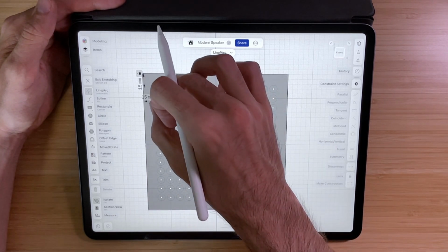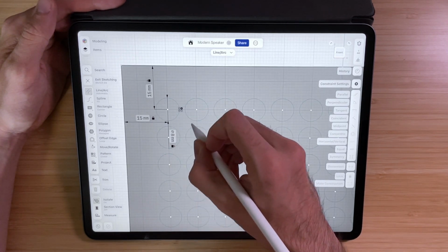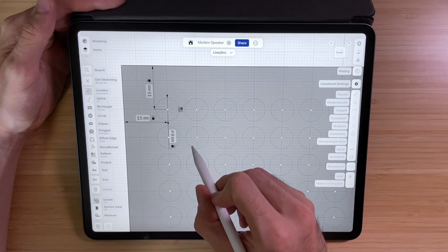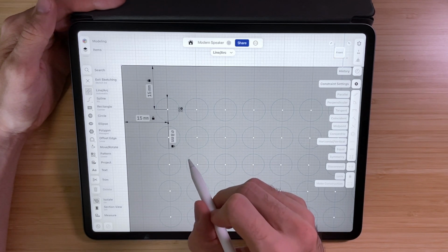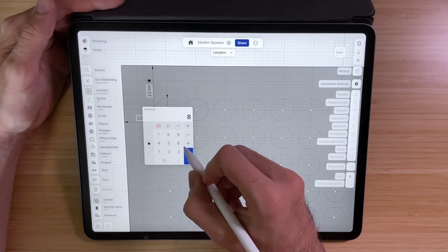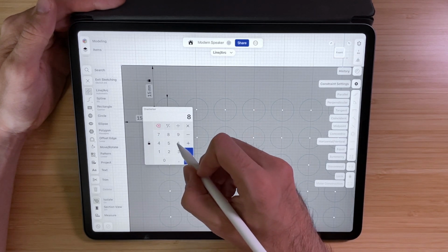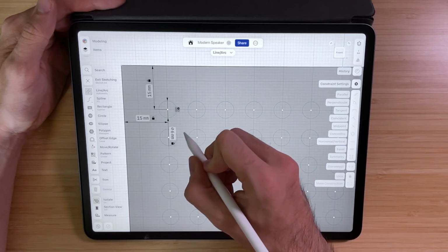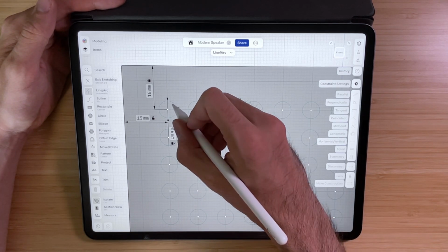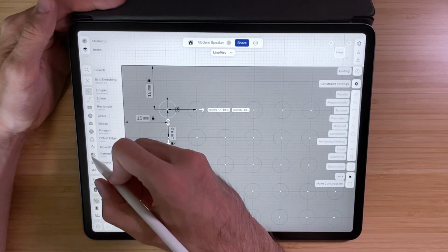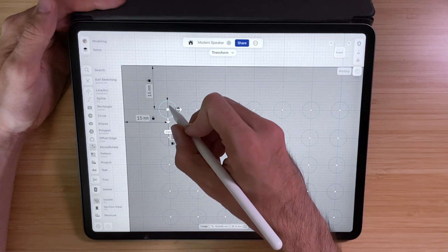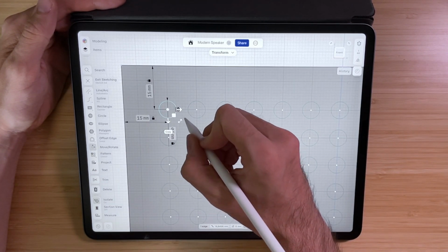So that means we would need to add another circle and another pattern here in the center between those 4 circles. And to do that, we also need to add a little bit more space. So let's change our diameter for the circle to 6. And then that would create a little bit more space for the new circle. Next, I'm going to highlight the circle and then go to move and rotate in order to move or copy this circle to the new position.